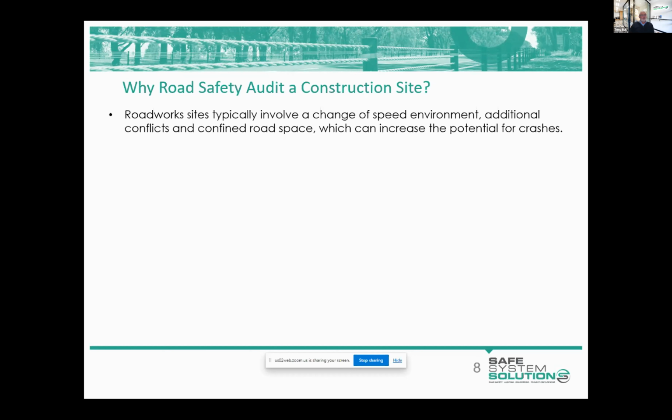So it's so important that advance warning signing is well placed and gives enough warning. It's not too far away, where we see a roadwork ahead sign, then don't see roadworks for a couple of kilometres and become oblivious to it. Rightly so, because if there's a roadwork ahead sign, we should be seeing roadworks.